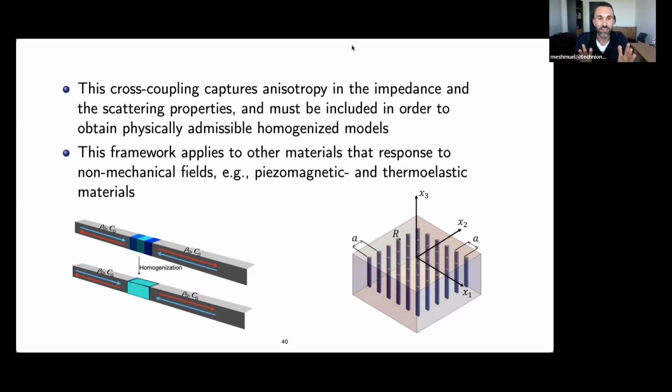Now, again, on a basic level, for flexural waves, the transfer matrices are also 4x4, right? We have the deflection and the angle, and the shear force and the moment, right? So I think that we can have that. And in this case, maybe I need to think about what are the modes that are going to be degenerate. In our case, it's a generalization of shear and pressure, but in bending waves, you said very thin, but maybe it will be antisymmetric and symmetric with respect to the midplane or something like that. So there is some potential, and this is interesting, and maybe worth looking into. So, Mohamed, you said that you don't have a mic, but I hope that you hear me, so thank you for the question.